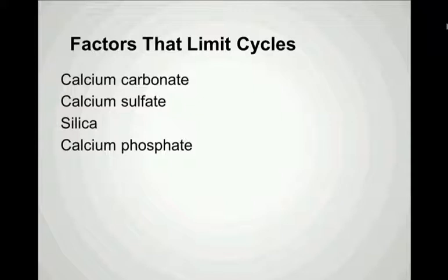So we can't operate the cooling tower at cycles of concentration that exceed the solubility limits of these insoluble or sparingly soluble salts. Otherwise, we'll foul the system with mineral scale deposits, and that, as we know, can rob us of efficiency, both energy and water efficiency.